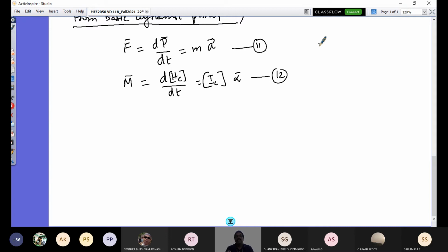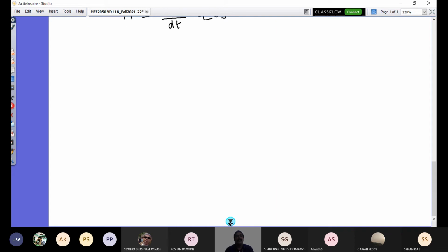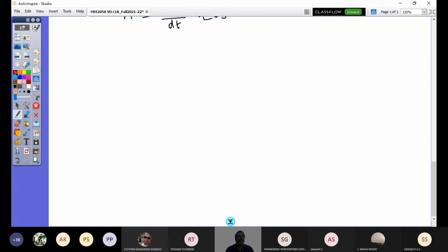So your differentiation, the acceleration in the alpha would be a bit involved. To understand that, let me give a generic vector A, because there are going to be more terms to come. It can be a velocity vector, acceleration, force vector, anything in a body fixed coordinate system. How do we differentiate that with respect to the inertial frame of reference is what we will write.